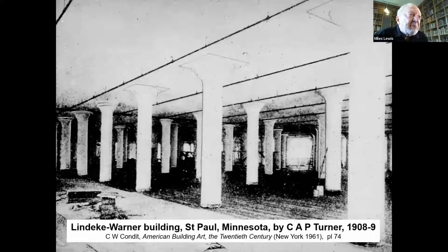Now, by making this flat slab, as I say, you've saved on the beams and you've saved formwork of the beams, you saved height. But you've had to create a rather odd system over the columns because the shear forces are very strong over the columns. So he's put in a square section, which is what's called a drop panel, and then an oddly shaped circular head below that, which is probably going to be quite costly to make. So he's lost half the benefit. He's also probably had to make the slab thicker to take all the reinforcement required, because he's putting in here, in fact, four-way reinforcement, as we'll see in a moment.